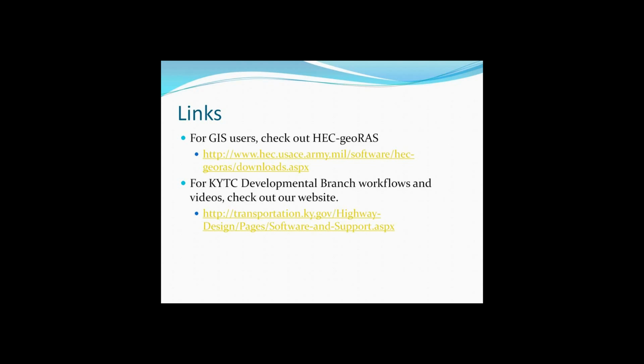And then I think on September the 3rd we're going to do a session on how, when my bridge doesn't look anything like the one in the example, we've developed a little process of using InRoads and XML reports to get station elevation data off of a baseline that allows you to deskew a skewed bridge.